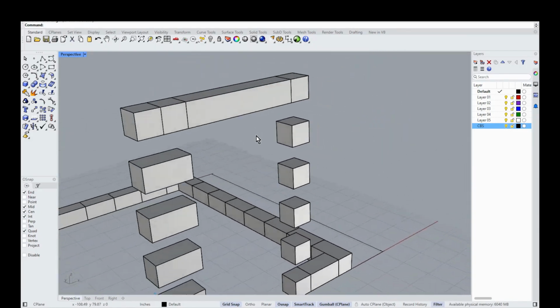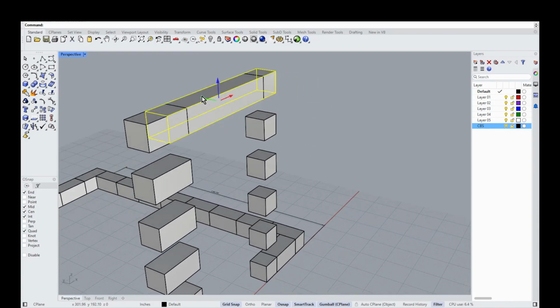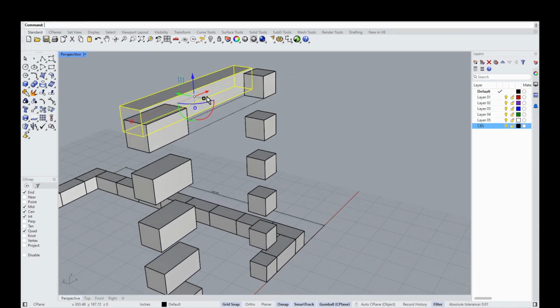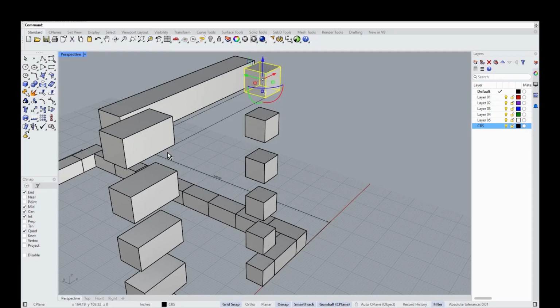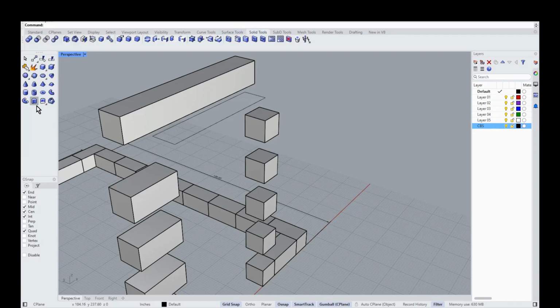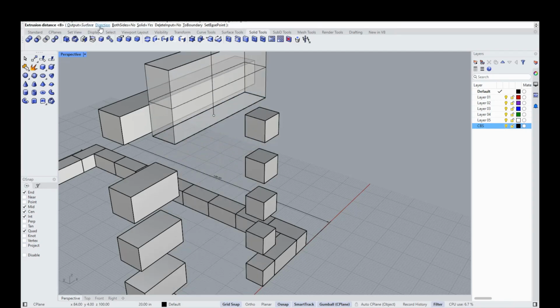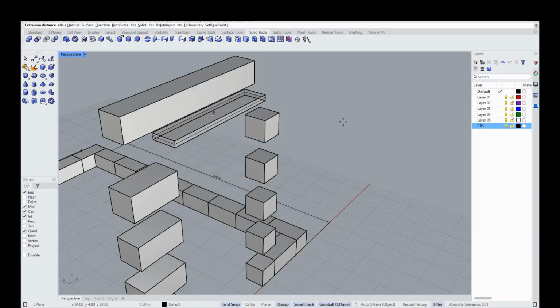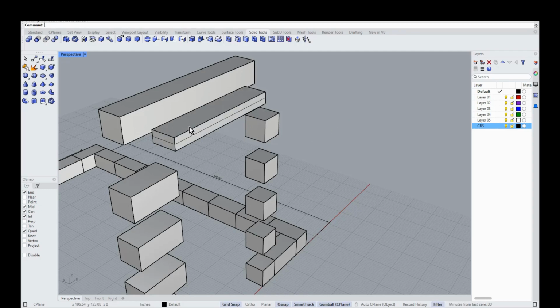So that's in there. And then I'll just say move this 10 inches away, so he's clear. Get rid of these. And then we're going to go back to solid and extrude it. And you can go in either direction, but I want to do something particular here. I want to go both sides, and it's like 2 inches. So this is going to be a subtraction object. And we come back over here, and then we go back -10.